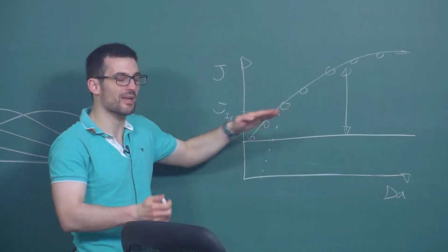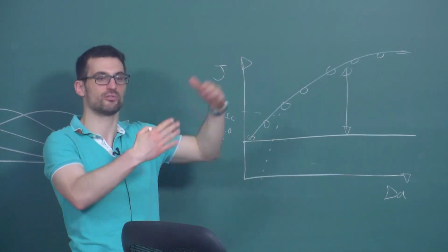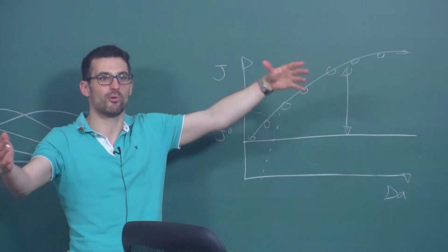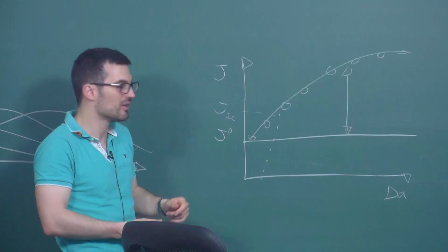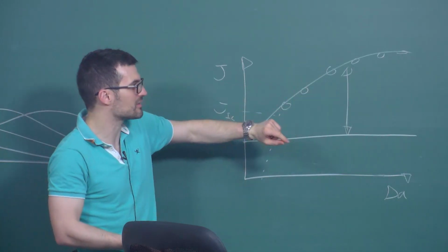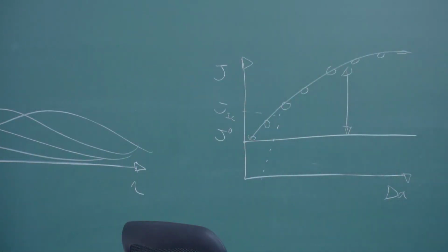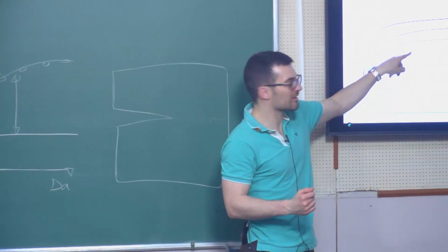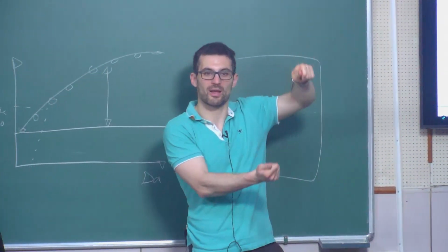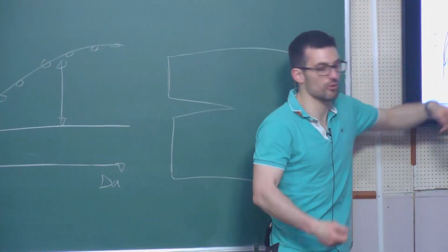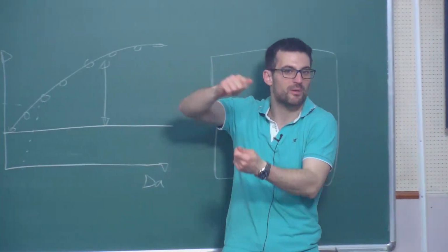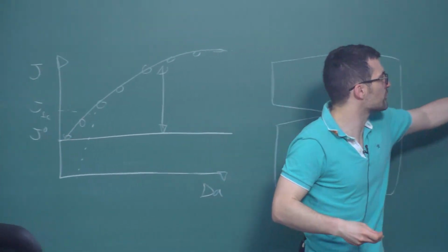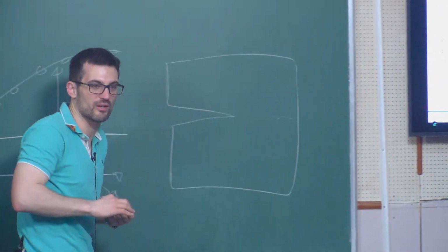It captures the fact that you may get less or more plastic dissipation, more or less toughening, in a component where maybe plasticity is a bit constrained relative to a big sample that you test in a lab for fracture mechanics. So this is what is nice about these models: without you having to tell how K, or J, evolves in time, these things are captured. You just pull, you measure your applied K, and you see how it's changing. You measure your load, exactly like an experiment. In an experiment, you measure your P, you relate your load to J, so you can relate your load to K, and then you see how these toughening effects come into play.